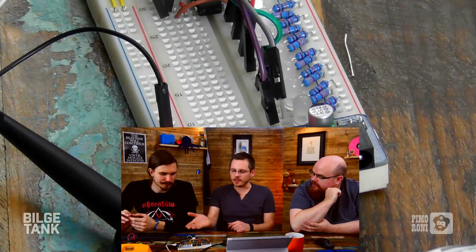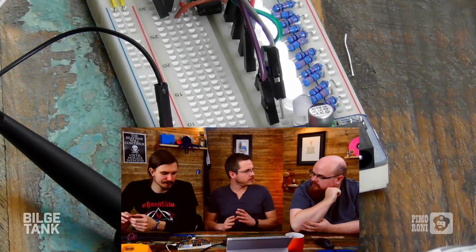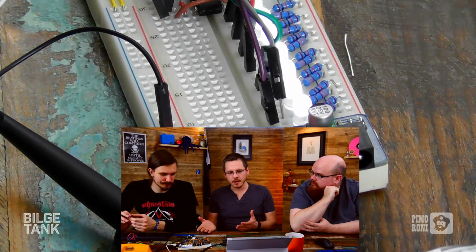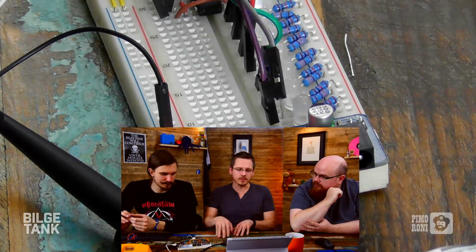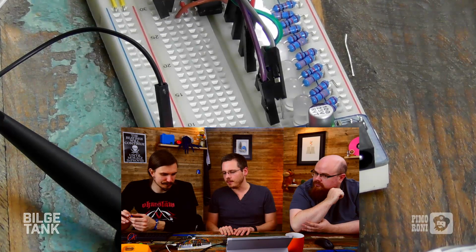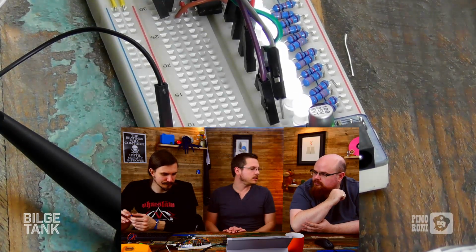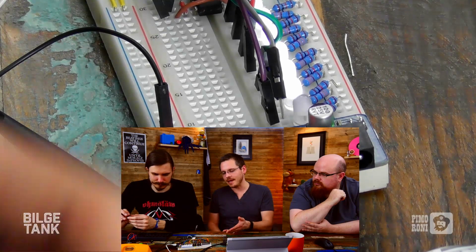Yeah. And you can actually do that using a load of diodes if you want to, or you can use an encoder that has 8 inputs and gives you a 3-bit output. Those are chips that are available. But yeah, that's basically how a parallel ADC works.